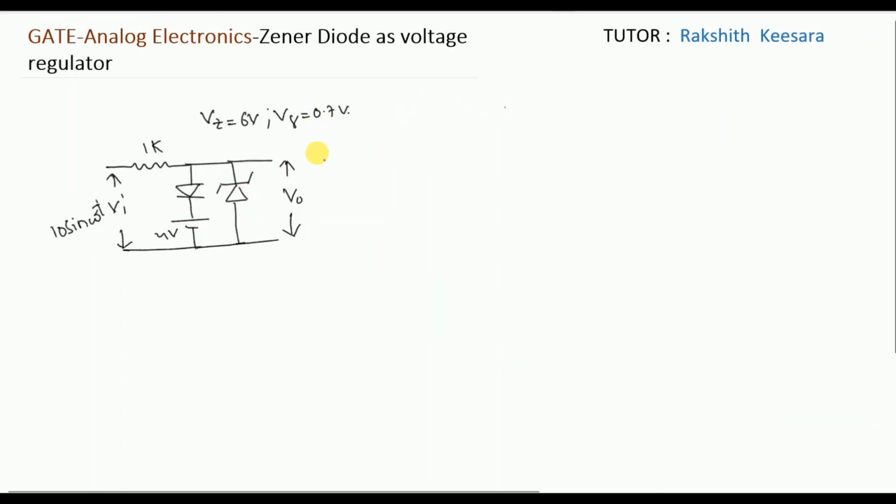And this is the last question, guys. In this, a diode and Zener diode combination is given. Which diode? Normal diode and Zener diode. So he gave the input voltage and he is asking us to find the output voltage. If you observe here, guys, if the two legs are not in operation, then V0 will be directly equal to Vi. V0 will change whenever either this leg or this leg are in operation. Then only our V0 will change.